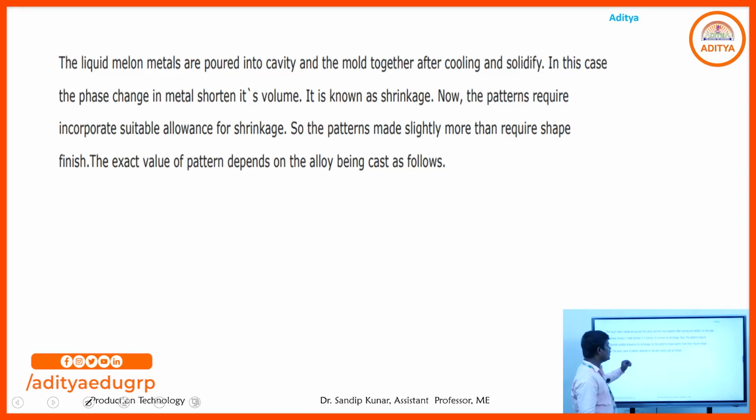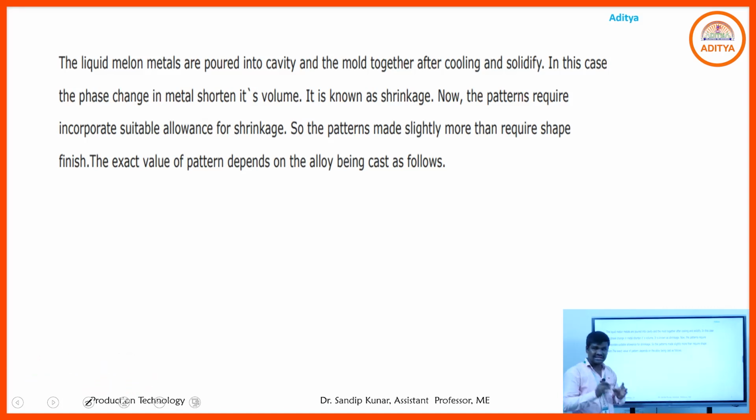Patterns are made slightly larger to compensate for the shape of the casting product. As per our requirement, the pattern may be slightly more than the required size, because due to shrinkage the solidified product volume will decrease.